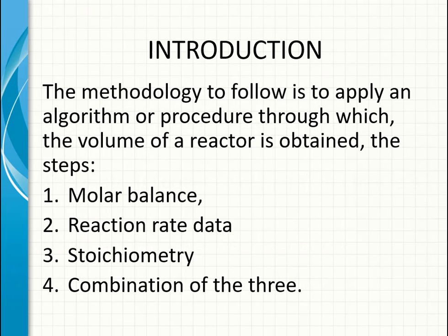The methodology to follow is to apply an algorithm or procedure through which the volume of a reactor is obtained. The steps: first, molar balance; second, reaction rate data; third, stoichiometry; and fourth, the combination of the previous 3.